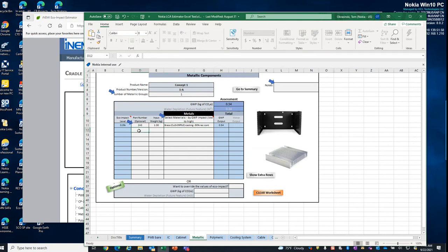If I wanted to then compare with another material, let's say, I'm going to go back in here and pick it alphabetically again by aluminum, die cast, 0 recycled content. It's telling me that I can do better than that; the lowest number in this category with recycled content is almost 23% lower. So if I wanted to, I can see where the hot spots are. As I put in my materials, I can focus on those areas, do what-if scenarios, and change those materials out and see what the impacts are directly. It's kind of a fun way to look at it, but it's also a very powerful way that we've set it up to do that.